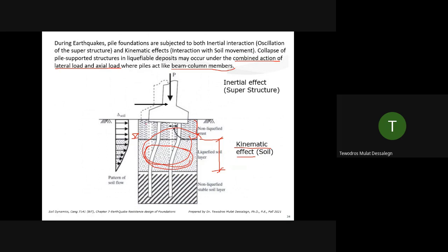So it can apply lateral load on the pile itself. You can see how the pile is bending right here, between the liquefiable and non-liquefiable soil, because this is like semi-liquid and this is a good soil. And let's say this is rock, and piles are located in rock, and this is liquefiable soil. So these pile portions are severely subject to high seismic forces from the kinematic effect. This is just the soil.